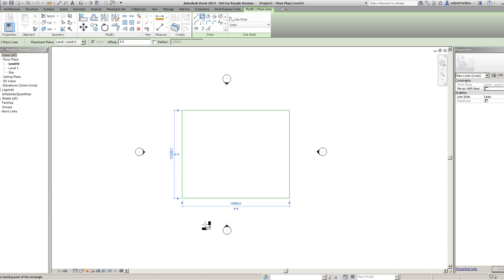What I can simply do now is left click on it and then change it. Remember, 16M for 16 meters instead of 16,000. Enter, bang, it just quickly changed it. On this one here, I want to change that to 10 meters, 10M, enter, done. Couldn't be simpler. Like I say, you just move it to where you want and then just bang it in, and then we just change the size afterwards.